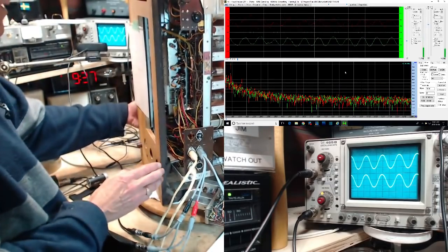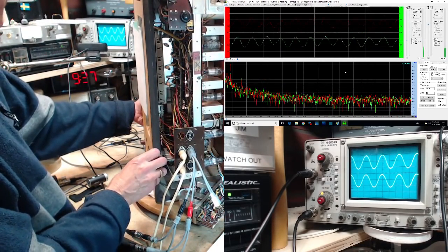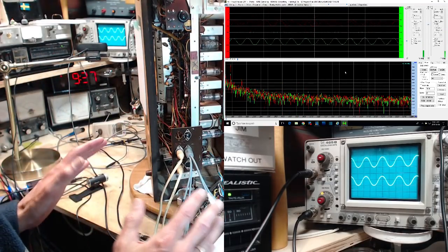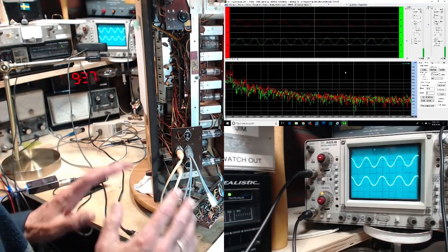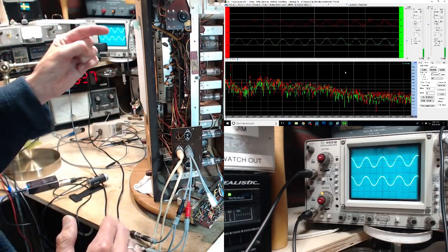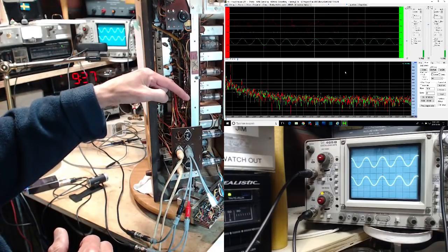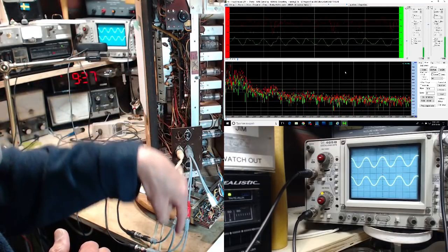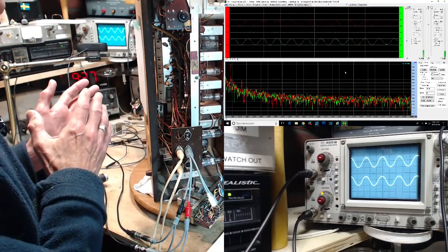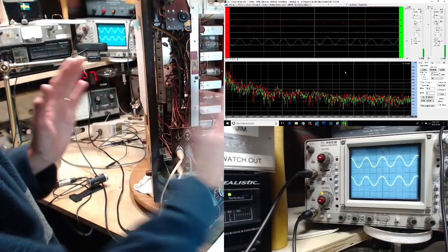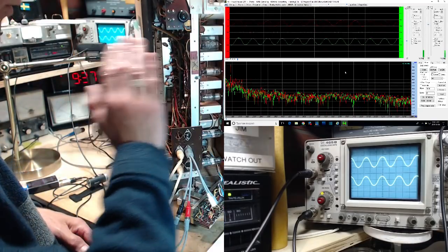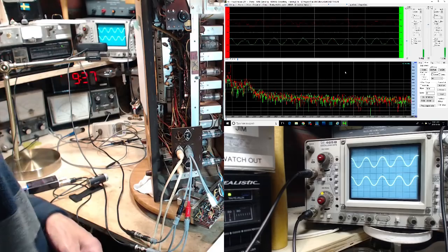I like that. The stereo button's been down all this time. Okay, let's repeat everything. Stereo button off. Now, I've looked in the circuit diagram about this, and when you switch off stereo, you actually feed the composite output coming from the detector straight on into the audio amplifier. Probably everything above the left plus right in the composite signal is thrown away. It's probably filtered out. So just the left plus right comes through, the whole thing bypassing this circuit down here completely.